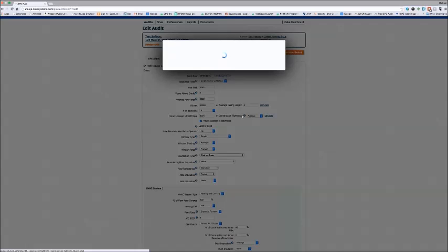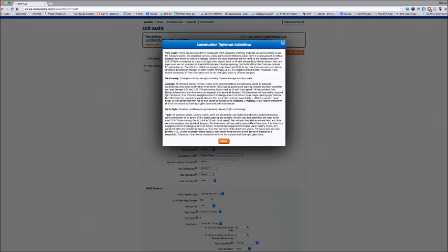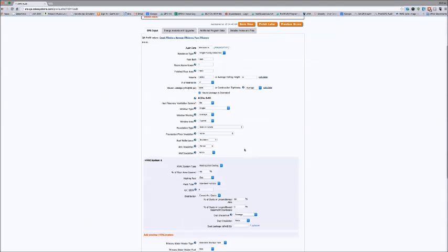So we've got a range from very leaky to tight, and we give you some guidance on how to characterize the house that would be in that condition, and then we make a calculation to estimate the CFM at 50 pascals. We also display for you what the ACH natural is. So where Blasnik's simple model really comes into play is in collecting information in these bucketed areas. So saving a lot of time on windows and insulation and things like that.